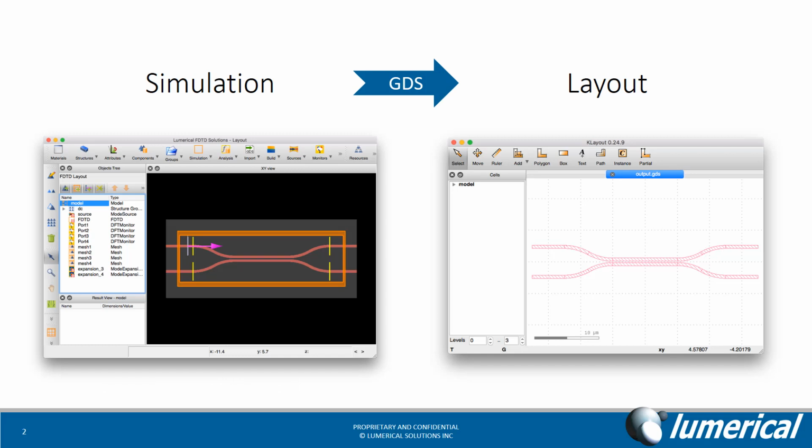However, in most cases, we want to do the opposite. We often start off with our component simulation tools first. We create the physical structures from scratch. If the structure is very complex, or if we want to parameterize the structure, we may use the structure group approach. Then we run the simulation, and if necessary, we run some parameter sweeps and/or optimizations in order to find the best design. And finally, we somehow convert the structure into a GDSII file as the final output of the design cycle and send it to the foundry for fabrication.